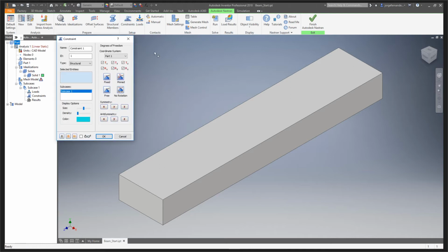All right, let's set up the constraints. You'll see here there's some quick options to get you started in case you needed to. You can always pick these boxes if you want to on your own. And notice also there's symmetry here. So if you have a part that's taking a long time to solve and there is symmetry within the part, we'd usually use one of those.